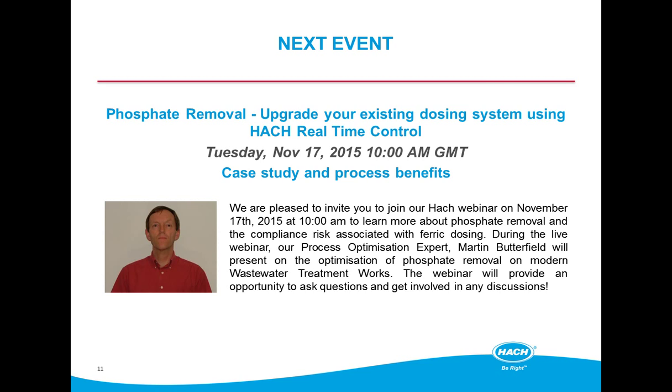He then tailors it to exactly what he wants it to do. So if there's any concern that having a minimum DO set point of 0.6 is problematic, he can just raise that to 1 or 1.5 if he likes. It's their decision to make to balance energy consumption with compliance risk.